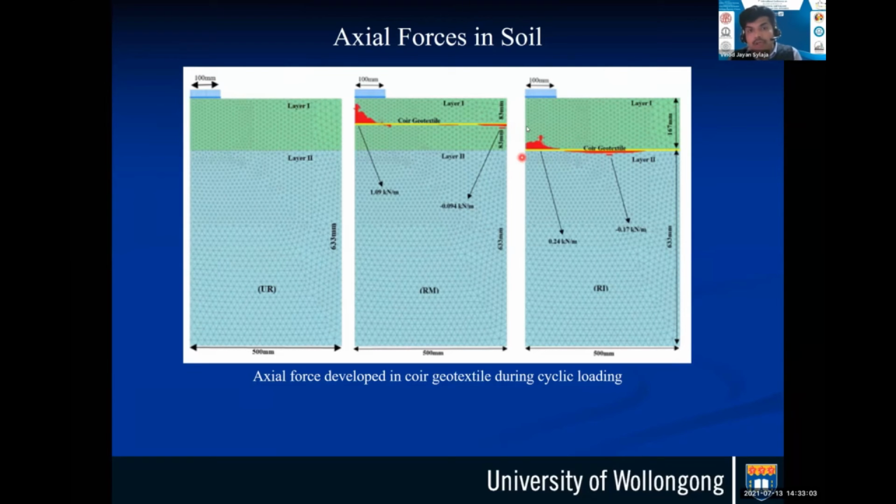That is probably due to the kind of load application that we have used. In the monotonic loading condition, we used a strain controlled approach, and here it is a load controlled approach. So there is a significant difference in the response of the reinforcement due to the type of loading that we are applying. Further, we need experimental evidence to confirm the findings that we have observed here. That is currently in progress.